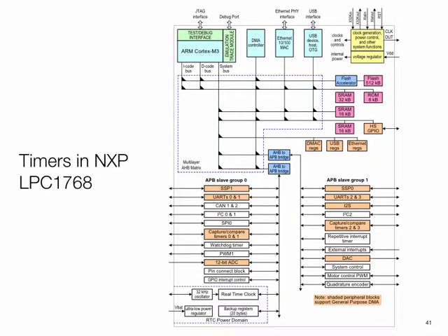If we go back to the slide, you would see a whole bunch of other stuff that you won't find in general purpose chips, like UART, CAN bus, which is used in automotive, I2C, which is another serial bus, and SPI, a serial interface that goes up to 10 megabits per second or so. So besides the timer part, there is also a whole bunch of interfaces which are very useful for interaction with the outside world.